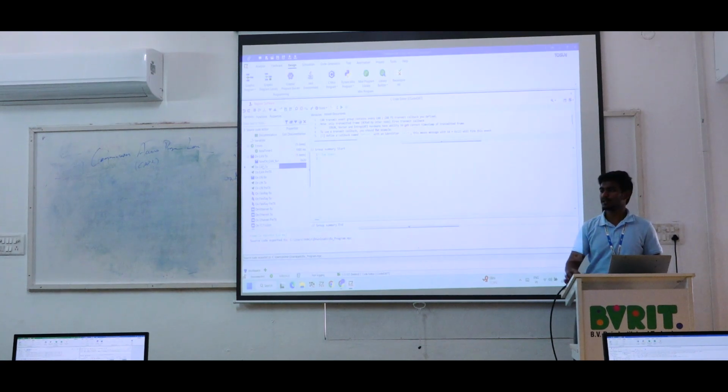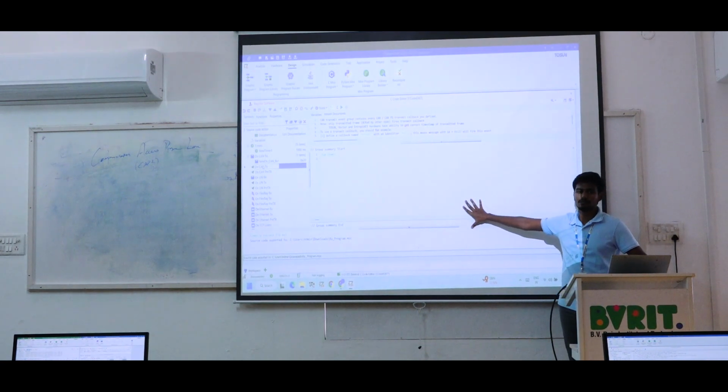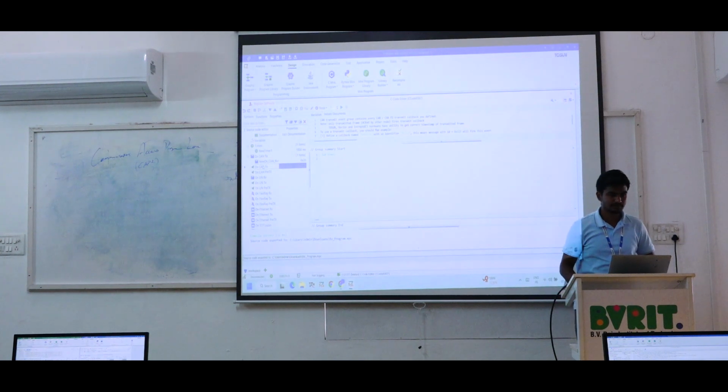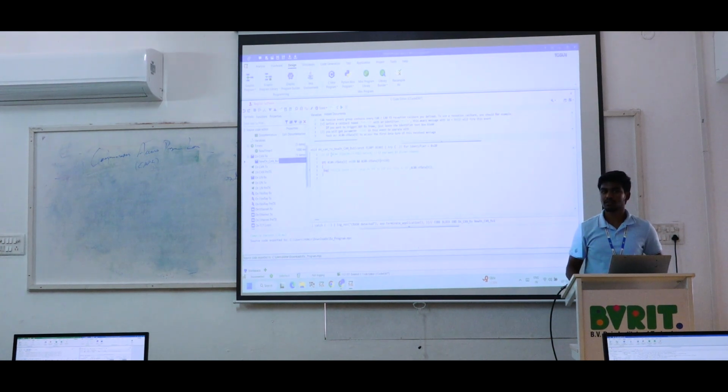TX is nothing but the messages we transmit from this tool, and those messages we are able to see here. For example, right click, add on TX. Go to TX, on CAN TX, right click, add on TX message. For example, the ID number. I have it in the same image, using the same script. Before, we worked up to on CAN RX, where we did some conditions. The second one is on CAN TX.